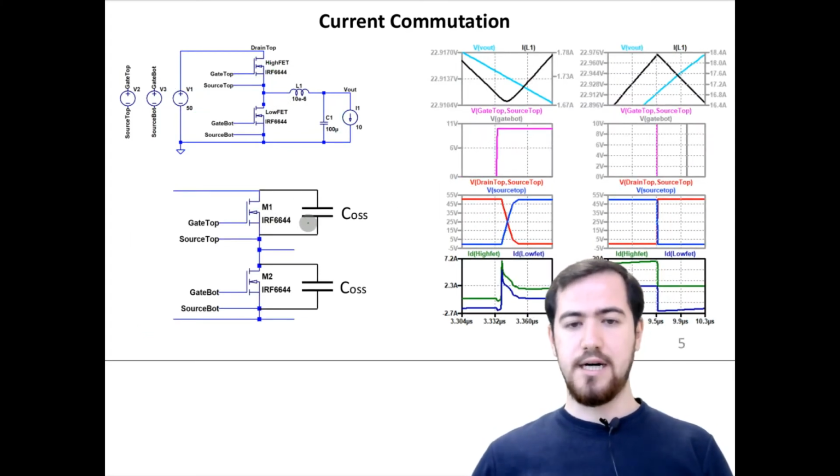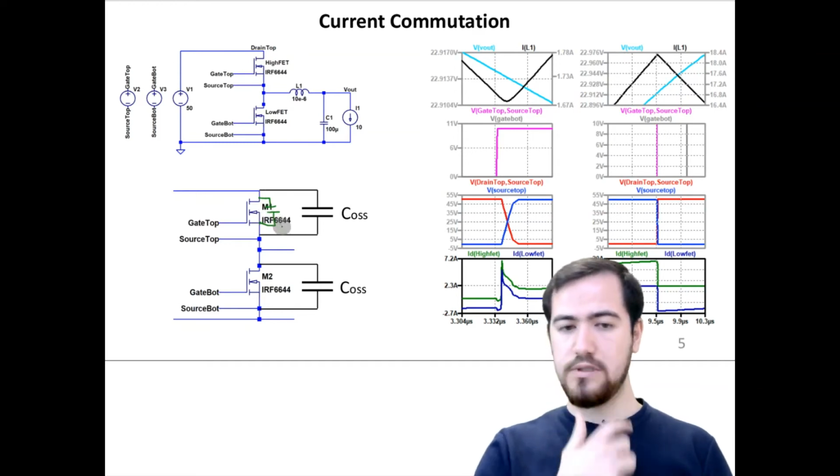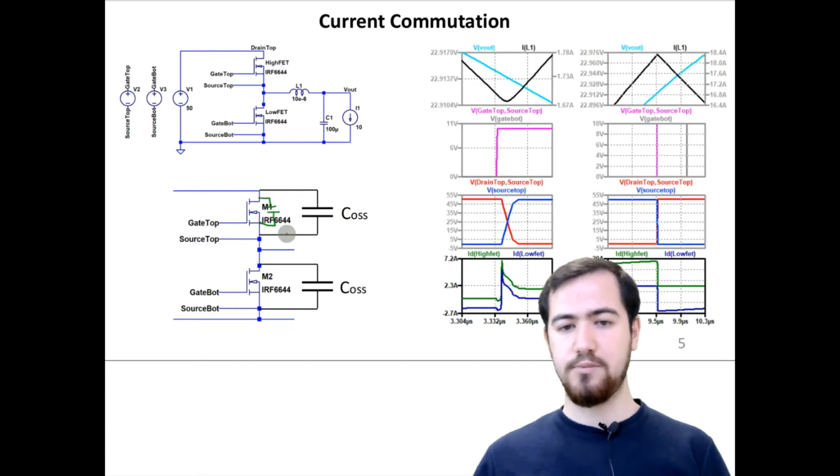important here, that is the output capacitance of the MOSFETs. As I said before, here the transition period is shown in a zoomed view. The current increases quite a lot. This is because at that moment the energy stored on the output capacitance of these MOSFETs actually needs to be charged or discharged, and this surplus current actually charges or discharges the output capacitances of our switching components.